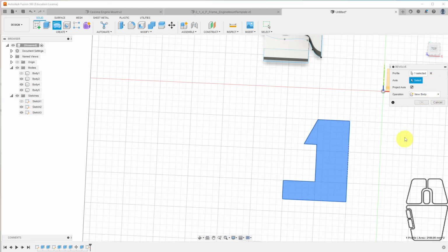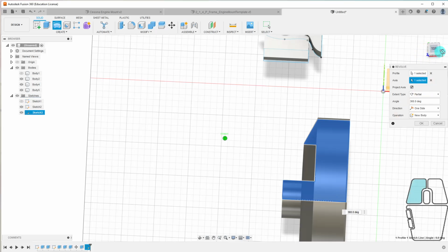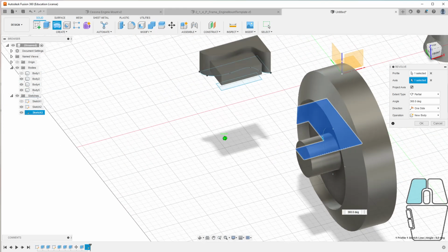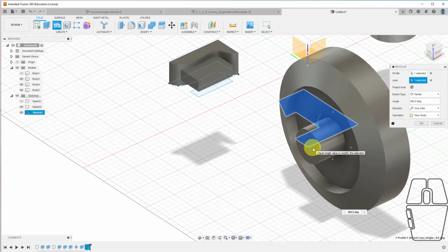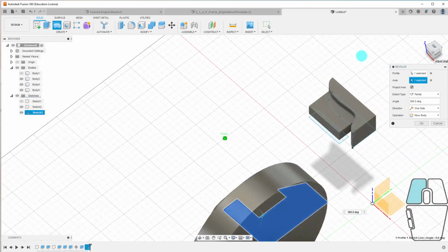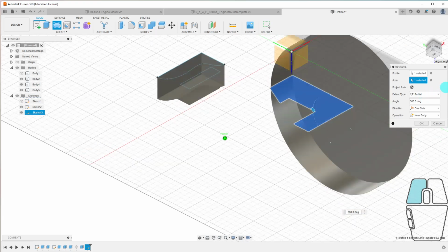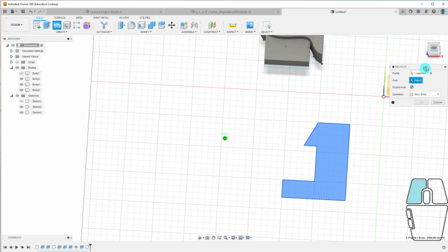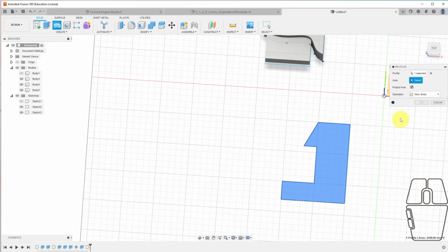If I hit the X, I can undo that and pick a different axis, like this one here. And so now I've got something like some sort of disc-like shape with this in the middle. Maybe it plugs into some other circular thing. Maybe it's the foot of the bottom of some object that sits on the floor, and this becomes adjustable if you put threads on this, and you can have an adjustable foot for the object that you're trying to support. So you can spin this around most any axis, but you have to be careful.